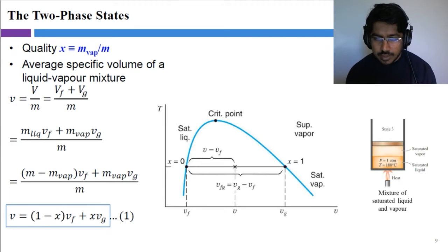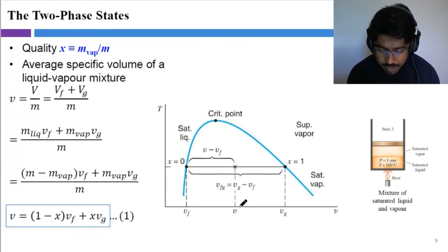Definitely. Good, Alexandra. We can mark it because you remember from our T diagram, the pressure and temperature inside the dome are related to each other, right? So if we know the pressure, we know the temperature as well. So if we only have pressure and temperature, we cannot mark the state, but with either one of temperature or pressure together with specific volume, we can mark the state, right? So that's what we have done here.